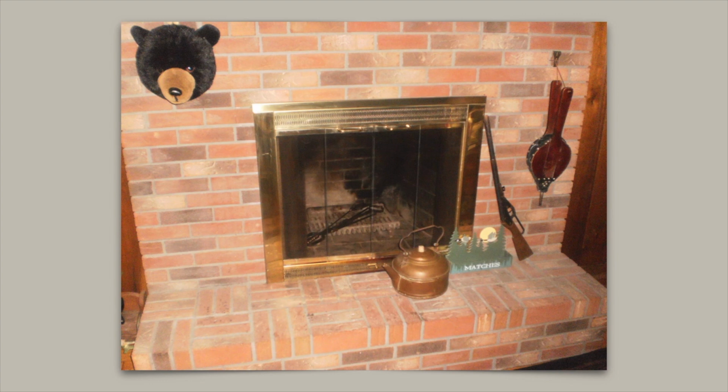If the liner has a visible buildup of creosote, a level 2 inspection should be called for before the closing. Creosote may be covering up cracks in the liner. Always recommend to your client having the fireplace cleaned before they use it the first time in case of hidden safety defects that you are unable to see.